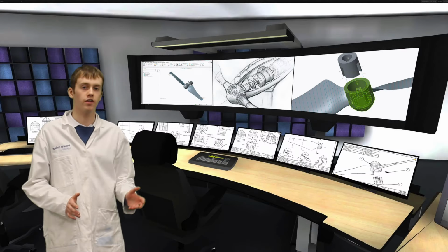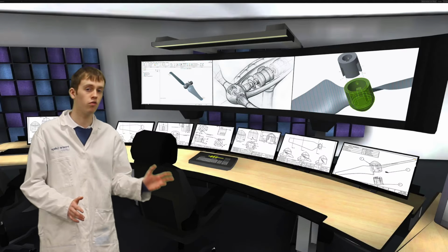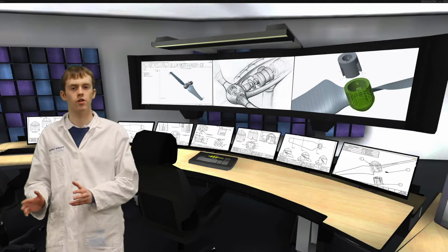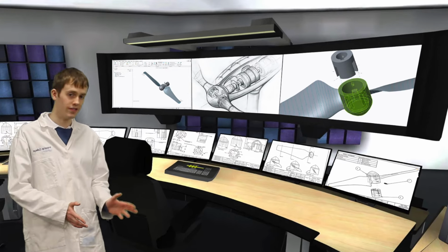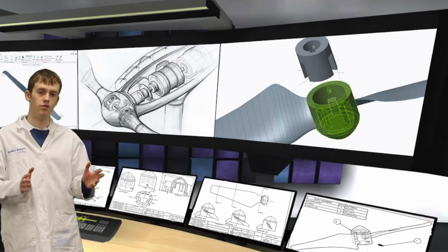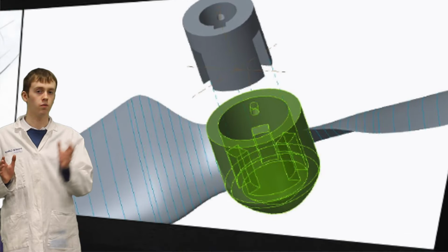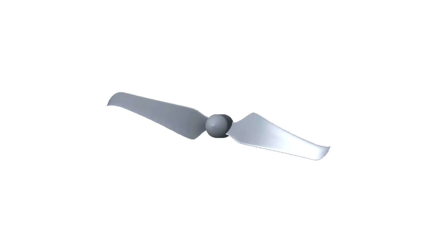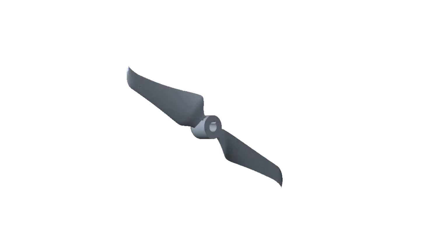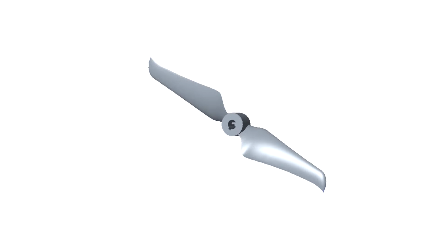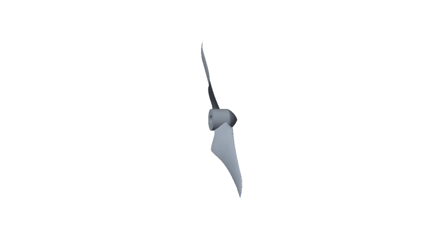The priority when designing the cone was for a design that didn't detract from the performance of the blade, but guaranteed a durable structure. In order to minimise material, the cone took the form of a hollow cylinder with a curved nose placed over one of the open sections. After investigating the benefits of elliptical, parabolic and ogive shapes, a Haack series formula was used to determine the shape of the nose, as its shape minimises drag. A single cone, comprising both the cylinder and nose, was then created in Creo Parametric before the finished blades were attached.